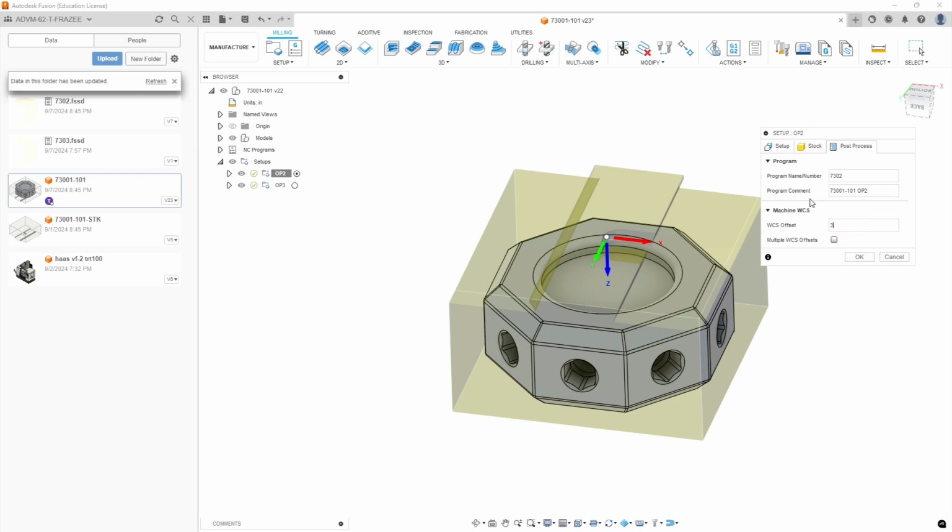And we're going to use work offset coordinate system 3, which is G56 on a Haas, and I believe we have that reserved for the rotary table. That way we don't have any interference from other classes, and we can still use the vise on G54 or 55.